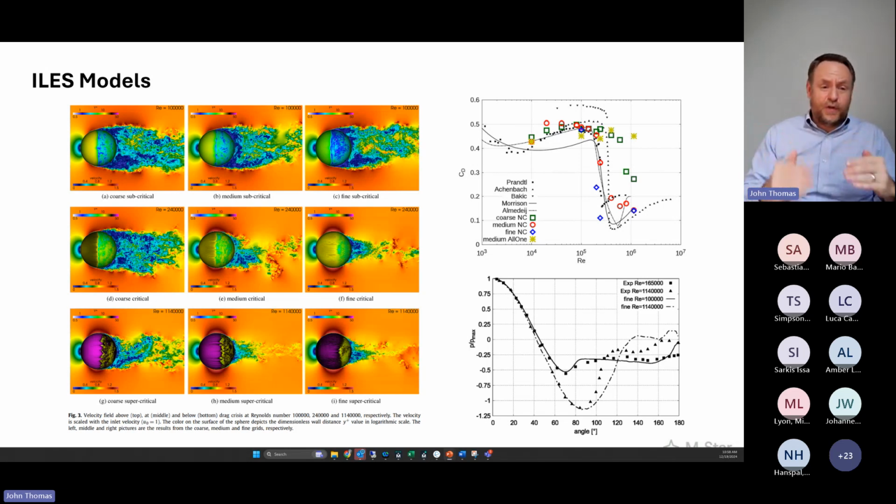Same thing with transitional flows. If you're doing a system with a strong variation in viscosity due to, say, some non-Newtonian effects, this ILES is awesome because we're not sprinkling viscosity into the code and therefore changing the rheology in a detrimental way. When you have systems where you've got to get viscosity right, whether it be some Reynolds number dependent transition criteria or some transitional flow, these implicit approaches are awesome because they don't adulterate viscosity, and they're higher order.